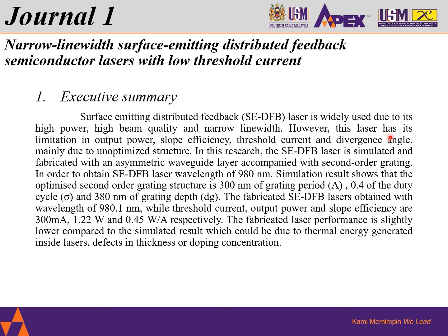However, this laser had its limitation in terms of output power, slope efficiency, threshold current, and divergence angle, mainly because of its unoptimized structure. Thus, in this research, the SEDFB laser is simulated and fabricated with an asymmetric waveguide layer accompanied with second-order grating. In order to obtain SEDFB laser of wavelength of 980 nanometer, simulation result shows that the optimized second-order grating structure is 300 nanometer of grating period, 0.4 of the duty cycle, 380 nanometer of grating depth.